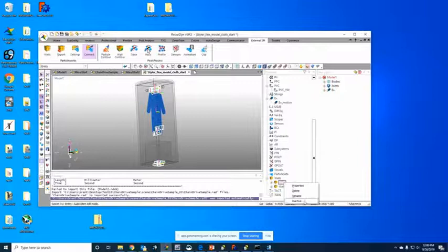These aren't great names, so I'll go ahead and redefine them. As you get more and more bodies, it becomes more and more important to name them correctly. So I'll change that first one to wall outer tank, and the second one to wall cloth FE. All right, so I have 2 walls that are defined for this simulation, and so now I can go ahead and click the export button.